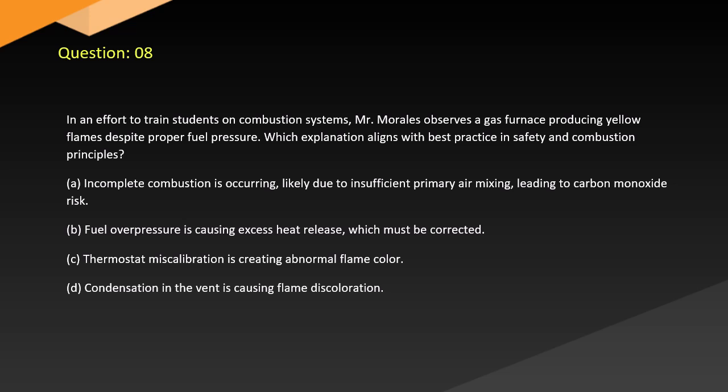A. Incomplete combustion is occurring, likely due to insufficient primary air mixing, leading to carbon monoxide risk. B. Fuel overpressure is causing excess heat release, which must be corrected. C. Thermostat miscalibration is creating abnormal flame color. D. Condensation in the vent is causing flame discoloration.